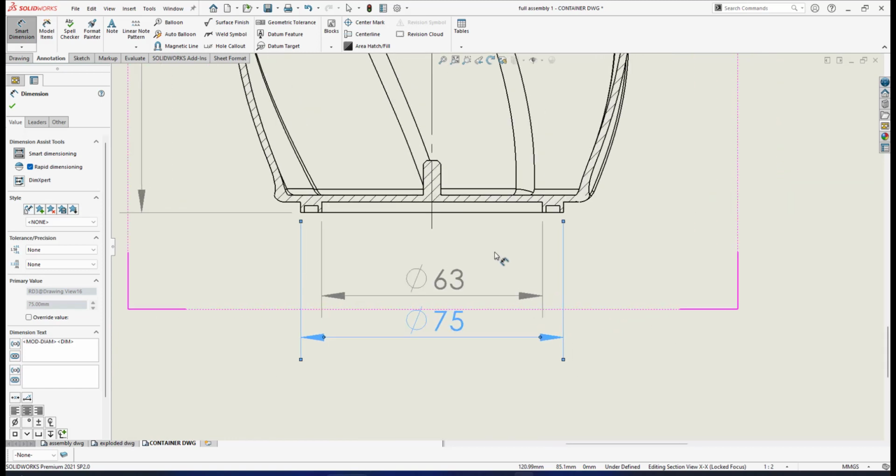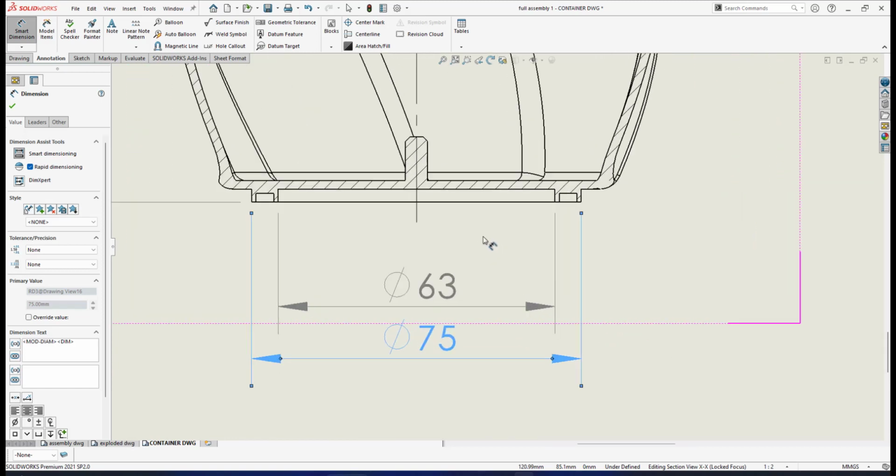Okay, another thing to mention is that if you use standard engineering drawing, SolidWorks will automatically put, since this is a step dimension, the level from your object to the first level of your dimension kind of too far. And also the distance between the first step and the second step is not what we want. For standard engineering drawing, as you know, the first level of your dimension should be at least 2 letter heights. Since the letter height is 3, it should be at least 6.